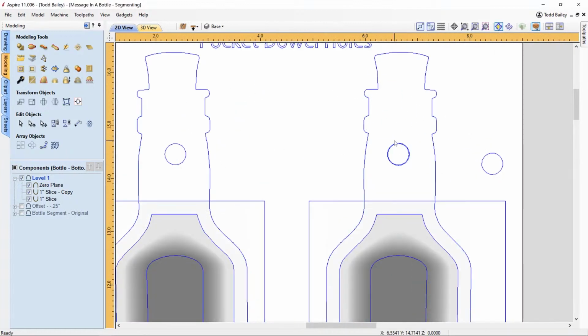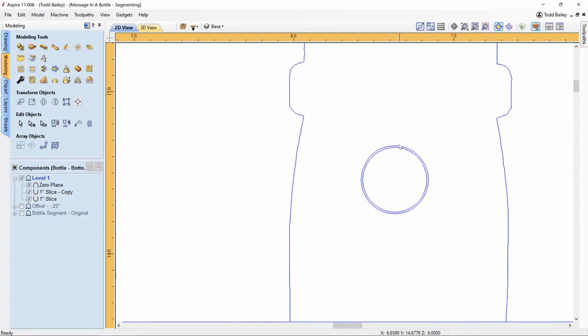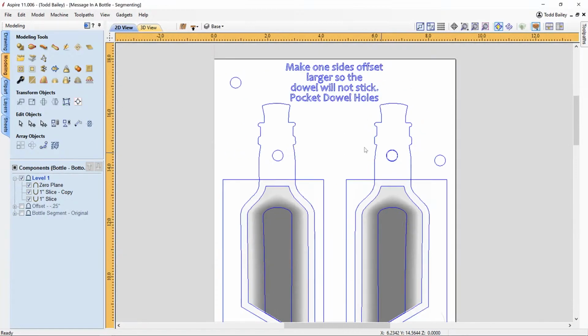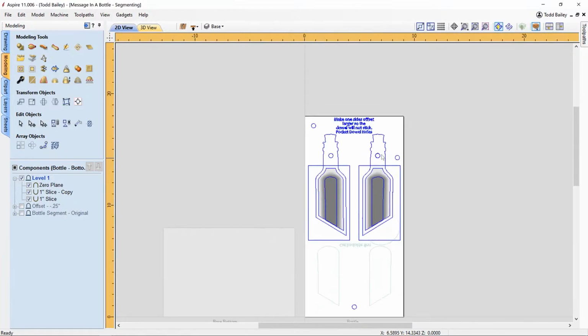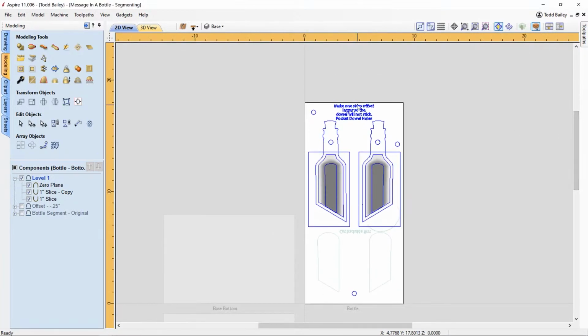I chose to use a vector instead of offsetting my toolpath because I only wanted one toolpath. So using this smaller vector and this larger vector, it was the same thing. It's just an offset from the original copy of that inside vector. So that does the same thing, and I only had to worry about one toolpath, not creating two. I was a bit lazy there, I guess. So that was pretty easy.